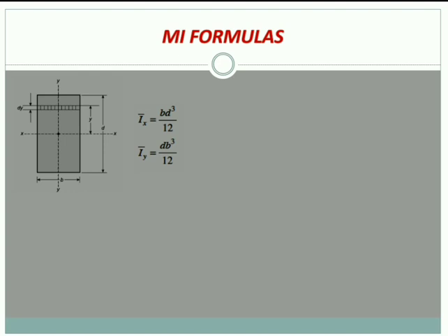Similarly, when we go for calculation of Iy, which axis are we considering? We are considering the vertical axis. So in that case, the perpendicular side is B, or width of the rectangle, so its cube we take. This is the simplest way, I feel, by which you can remember which cube you have to take. While calculating Ix, take the cube of depth; while calculating Iy, take the cube of breadth.